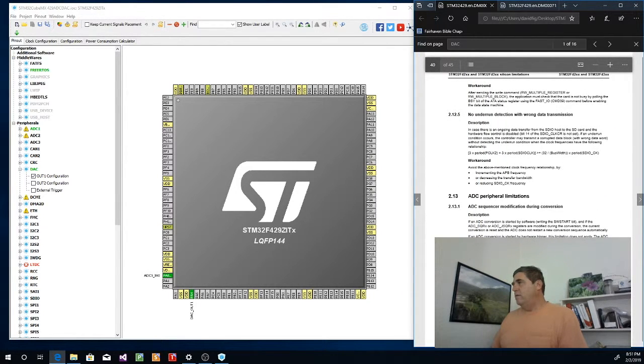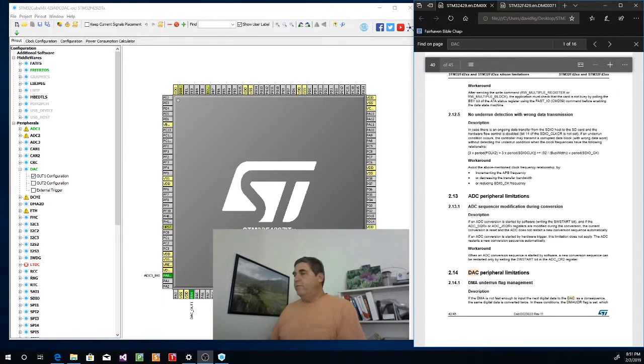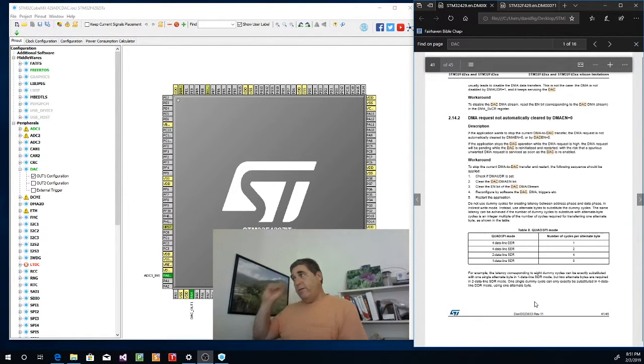Oh, we kind of have a problem here, huh? So let me move the video out of the way for a moment. So it says here, if the DMA is not fast enough to input the next digital data to the DAC, as a consequence, the same digital data is converted twice. Okay, I understand that. So basically it's saying that if you put data in and then the DMA is DMA'd again really quick and you haven't changed it, it's going to put the same number in. So in other words, DMA transfer may be timer based, or there may be some issue with that.